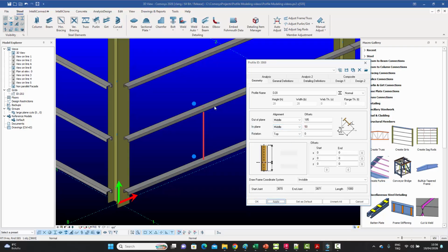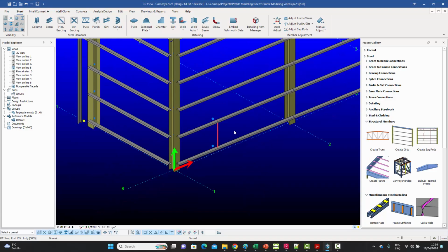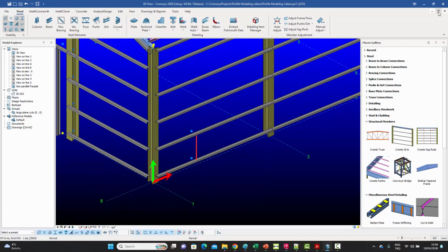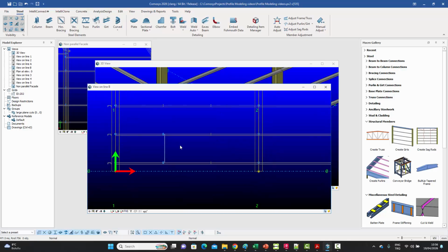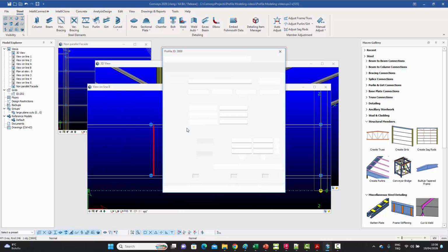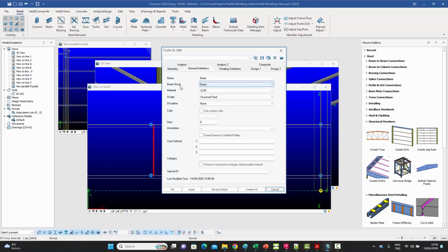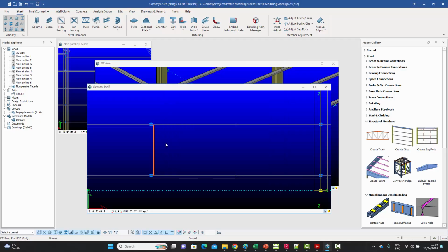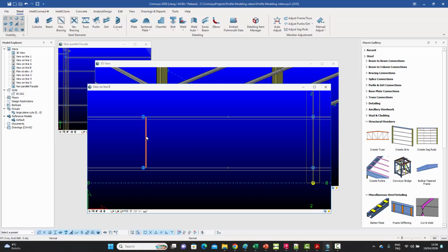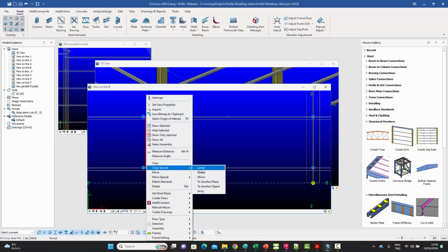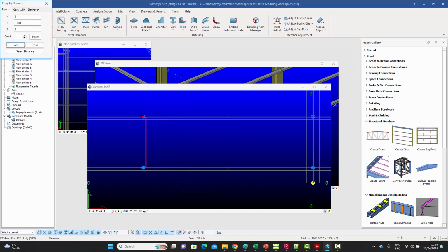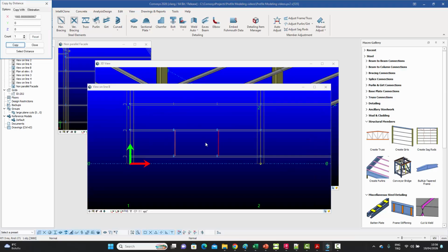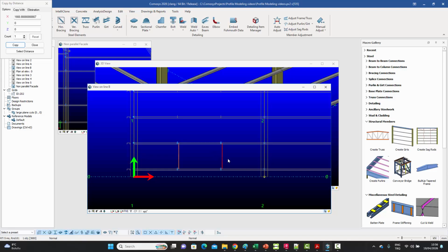It's gone in that direction, if you notice. Now that I have that, I can go back to my other one. In fact, before I copy, let me just convert this beam group to a sag rod rather than a beam, because that's also going to be helpful later on, maybe. And then once I'm done with that, I can just say copy linear from this point to this point, like that. And I've got my first two sag rods in there.